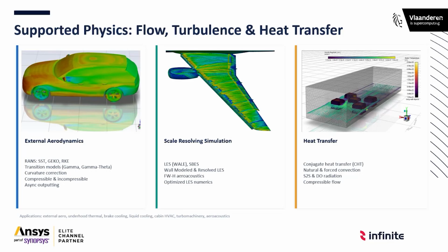For external aerodynamics, we can run the full range from RANS models, transition models, including curvature correction, and also both compressible and incompressible flows can be solved. Even on the scale resolving simulations, we have a lot of possibilities.